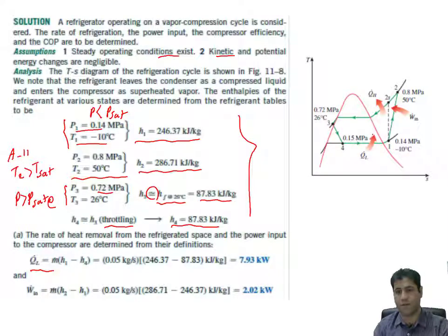This process, we have Q dot L, so changing the enthalpy, because we have already ignored changing the energy due to the other changes in the system. And also, I have already discussed in the previous session how we can find Q dot L from the cycle. It's based on the first law of thermodynamics. And we have already found this equation for this cycle: Q dot L equals m dot (H1 minus H4). M dot, H1 and H4 we have already found here.